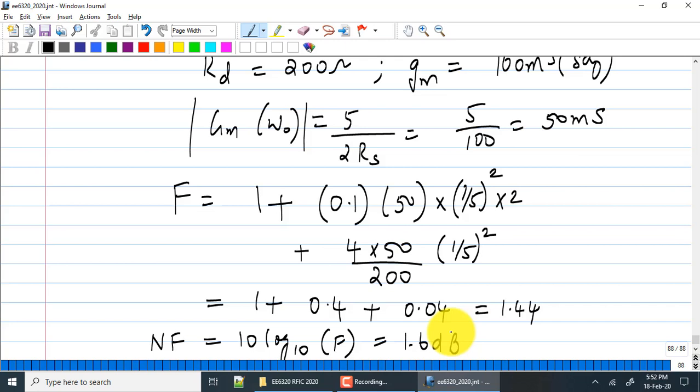So if your Qn keeps increasing, which happens at higher and higher frequencies, what will happen is that the effective noise figure that you can still achieve, as long as you are far away from omega t, can be really, really good compared to, for example, the common gate or the resistively matched input, where you have the shunt resistance at input, because of the passive gain from the input match. How do you increase that passive gain? How do you get even better noise figure? I want to push down the noise figure. How do I do it?